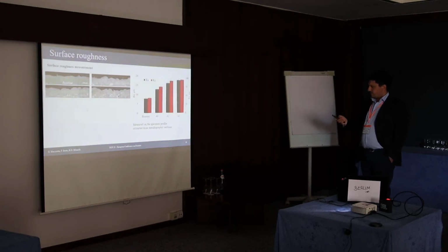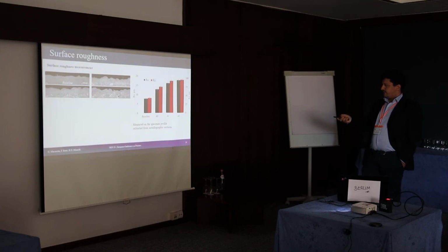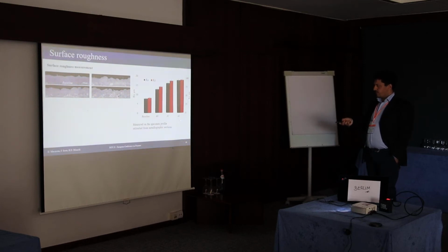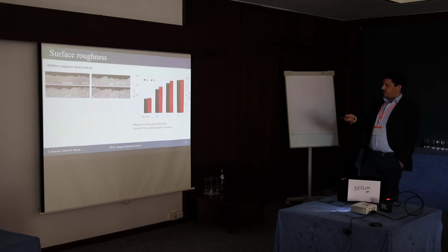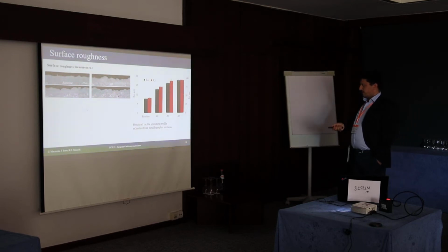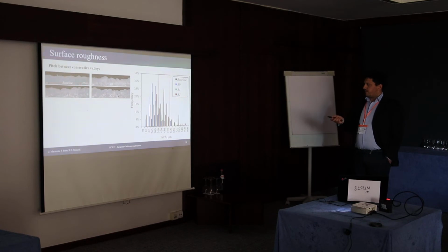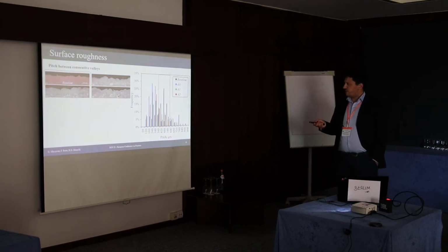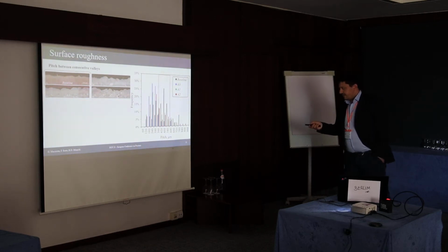If we look at the roughness measurement, obtained from these profiles by image elaboration, we can see that the roughness increases monotonically from baseline to A2 process parameters. As the process was sped up and the melt pools are more elongated, the process is more unstable, and so we see this increase in the surface roughness, both in the average and in the total range of the roughness. The other interesting aspect that we observed is the variation in the pitch of the roughness. While in the baseline case we see this waviness, the average, most frequent value of the pitch between two consecutive valleys is 418 microns.